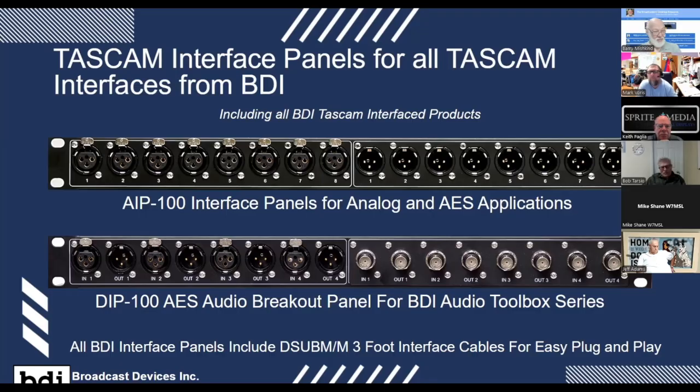So we make these in various configurations. The AIP 100 interface can be used for analog or AES applications, and we supply 3-foot Tascam cables with each one of these panels. So there would be 2 cables for each panel. That's a standard male to male, and they're all AES-3 compatible, all shielded balanced pairs. So we get good integrity going to our equipment, anybody else's. Now, I will point out one thing. If you look at the bottom panel there, the DIP 100, which is our digital interface panel, it's made specifically for our AES-3 IO.